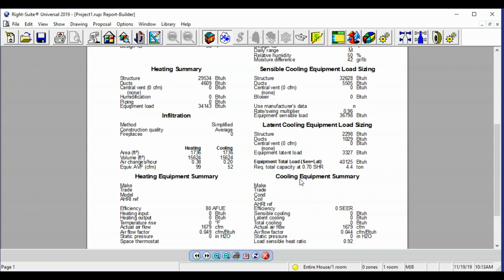But in this instance, some areas do things their own method in their own way, despite what the recommendation is. So if you were sizing per sensible, and your sensible heat ratio was 0.7, then you would need a 5-ton unit for this house to make it size correctly.